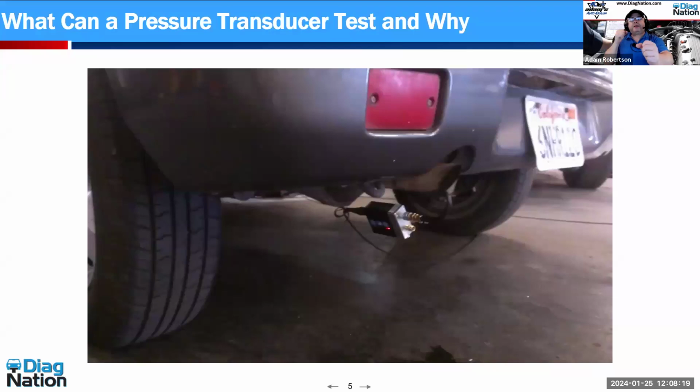Every time a cylinder fires, there's going to be a mass or a volume of expanded gas that comes out the tailpipe. But the tailpipe isn't a smooth action. The tailpipe isn't constantly running that exhaust that we see when it's cold. It's actually a series of these pulses. It's the 1 3 4 2, 1 3 4 2. But one of the things to consider here is what happens in between those pulses.